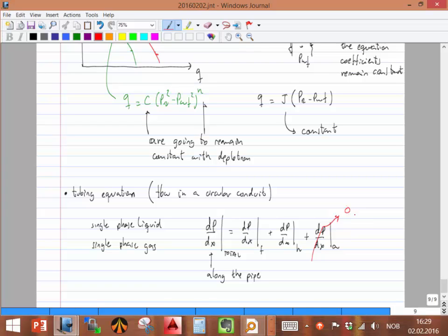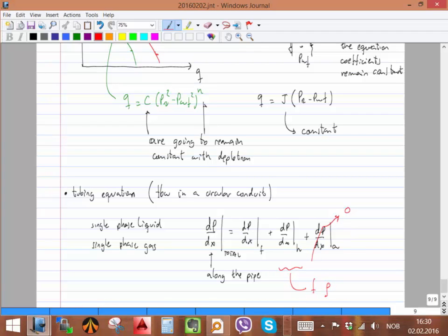And hydrostatic, you have the intuition that it is a function of density, the density of the fluid that is circulating, and that's a problem for gas. For liquid, the density doesn't change much with pressure or temperature, but for gas there is a very strong dependence on pressure and temperature. So as the pressure is decreasing along the tubing, you have a change of density. That's affecting this term, and also affecting the delta H, the difference in height.